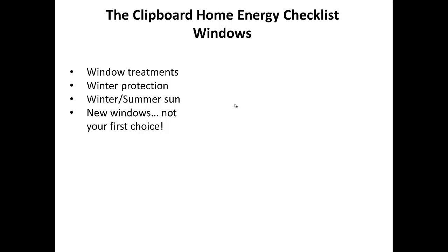And I should also say that another benefit of an energy auditor that's professionally trained is that they're also trained about the safety of furnaces. In the first paragraph on the home energy checklist, at the very top, it says that it's very hard to do, but if you've got an old furnace and you work really hard on making your house airtight, you can make your home so that it is dangerously unhealthy, because you're not getting enough fresh